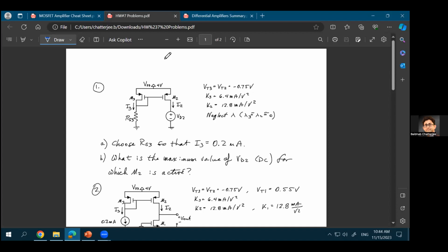You have your P-type charge carriers, or positive charge carriers, which are the holes. And holes, again, flow from source to drain because source is the source of something. Drain is, again, the sink of something. That definition of the English word does not change depending on whether it's a PMOS or an NMOS. Now, if the charge carriers are flowing from source to drain for the PMOS, the current will also flow from source to drain, because it's positively charged carriers which are flowing from the source to drain. So for PMOS, you'll see that the current flow is from source to drain.